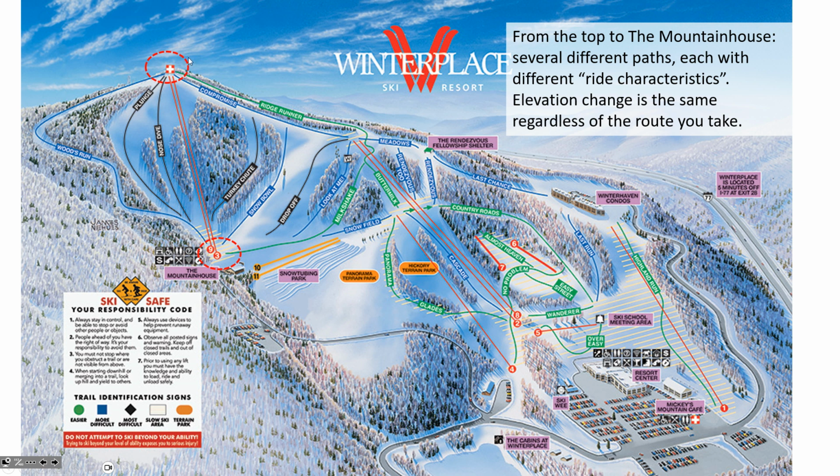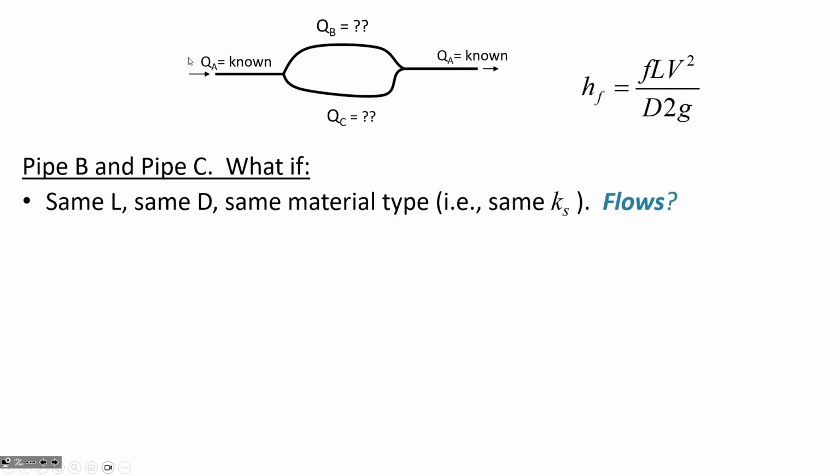So your energy loss doesn't matter whether you go on the steep run or on the shallower slope run, your energy change is the same. So how does that relate to this? Here's what we know. Some of the water will go through pipe B, some will go through pipe C, but regardless of which route you take, the energy loss is the same.